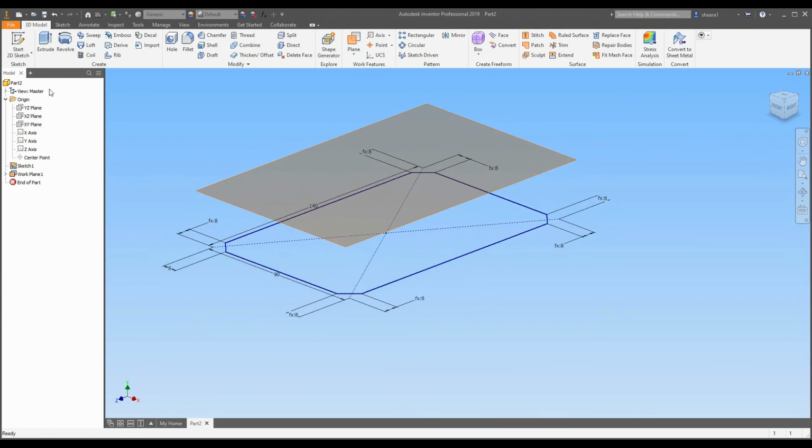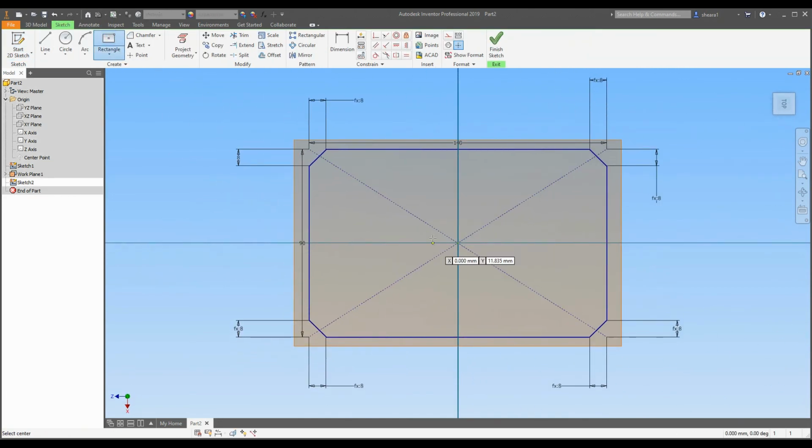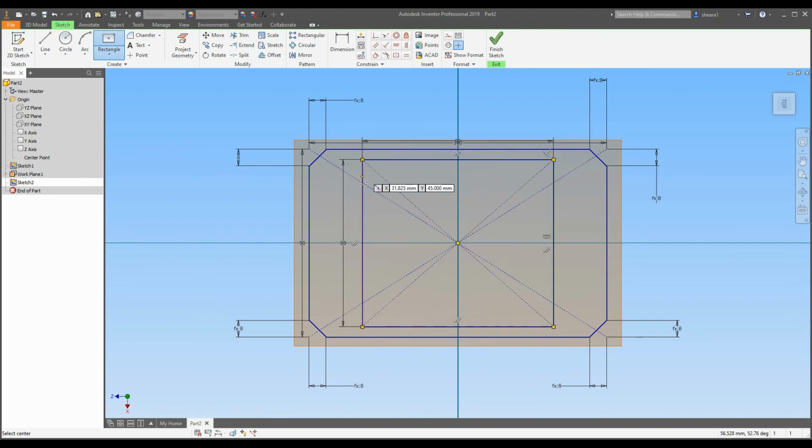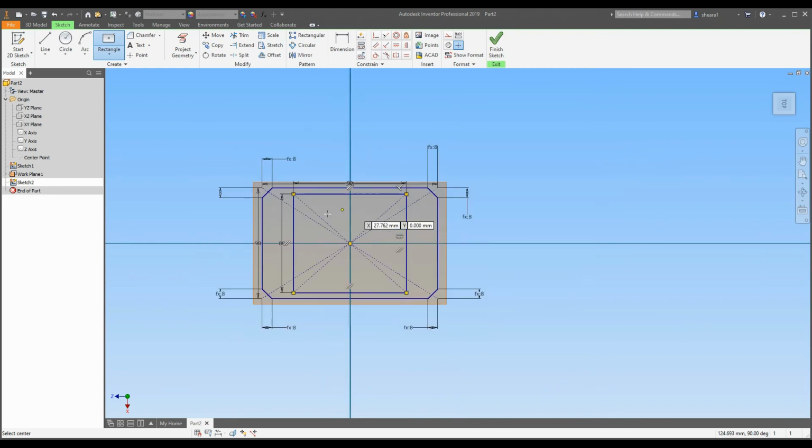So basically, I'm going to use the Loft tool to connect the sketch on this plane and the sketch that we're about to make on this next plane. So let's just go ahead and make our sketch without further ado. It's going to be another rectangle, this time 80 millimeters in height and 90 millimeters in the width. And there we go, we've got another rectangle on the inside.